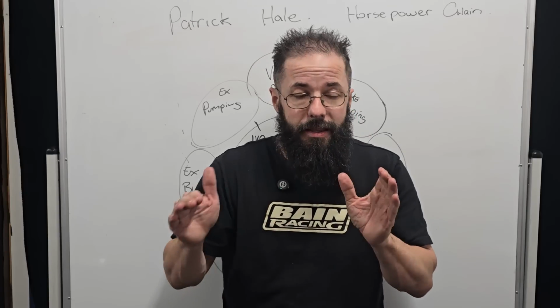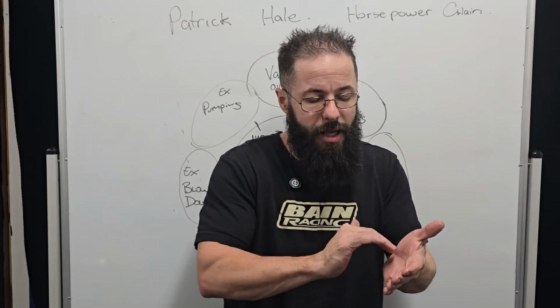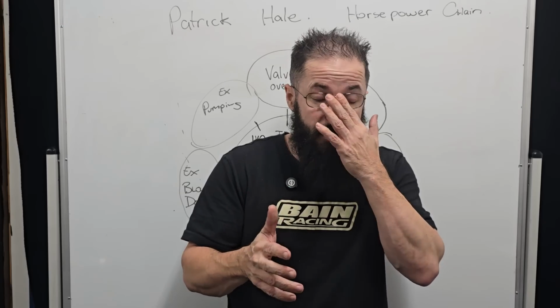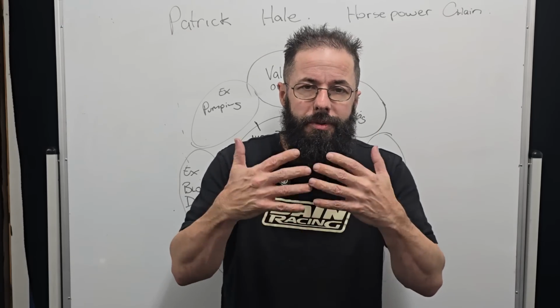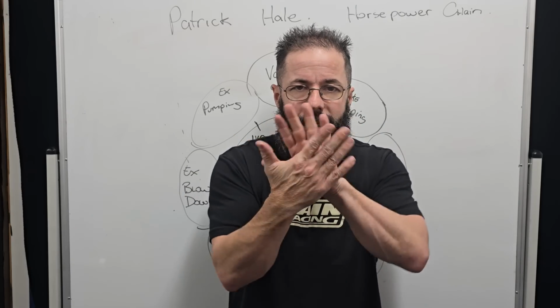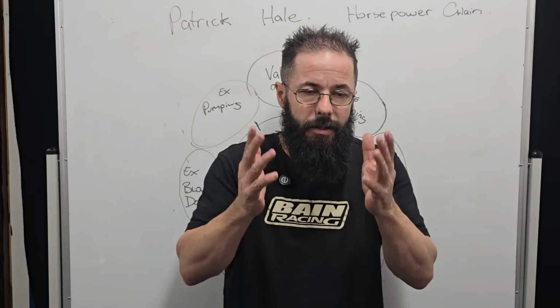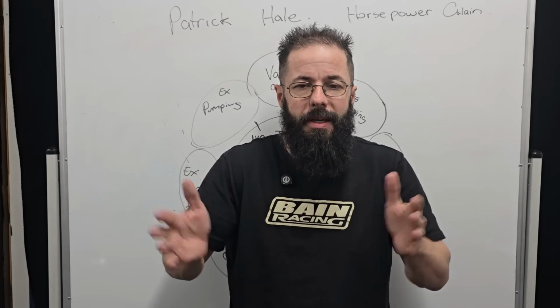But Dave talked about this leakage and really, really long ramp. So we would see it in cup cars and stuff like that. We'd look at different camshafts because we used to use different masters and put them on the same profile and then set our LSA. And most good engine builders do this day in and day out. The average guy probably doesn't know, hence why I'm explaining it.